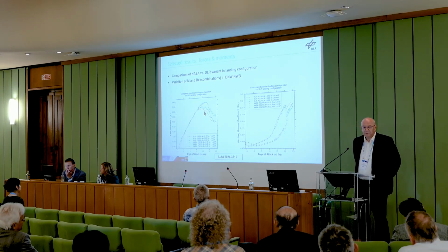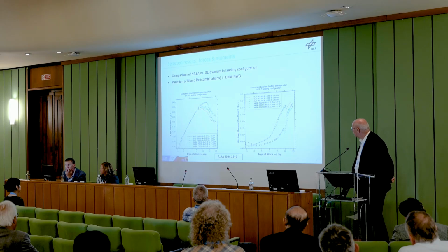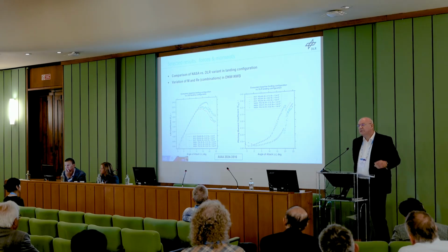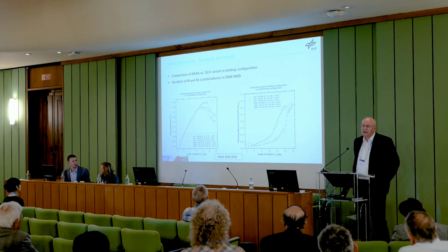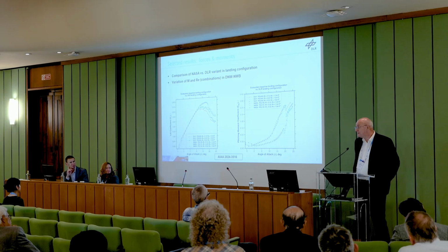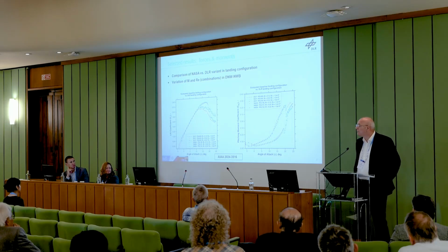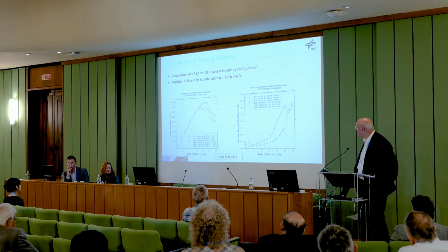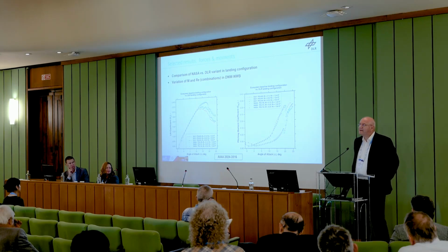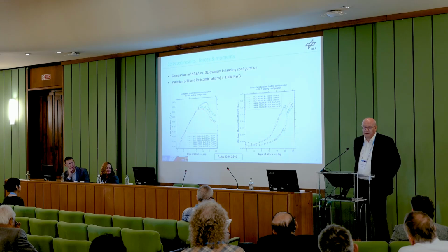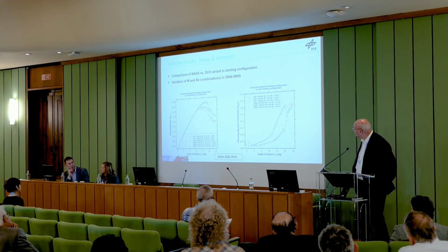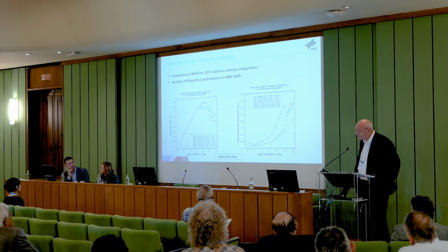So if you go to reference conditions, that is Mach number 0.2, we have a degradation of CLmax of about 20 lift counts. Having the possibility to check and change the single components tells us that basically this is due to a separation trend at the outboard Krüger at these low Reynolds number conditions. As I mentioned, the design has been made for full scale, where we do or did match the NASA performance. So this is a clear low Reynolds number effect, and it's also attributed to the links or the brackets of the Krüger, which have been designed, let's say, following the slat tracks or the slat brackets, as we didn't have the freedom to adapt them. So half of that is due to the brackets, and half of that is due to the low Reynolds number.